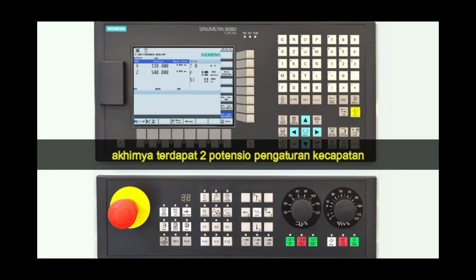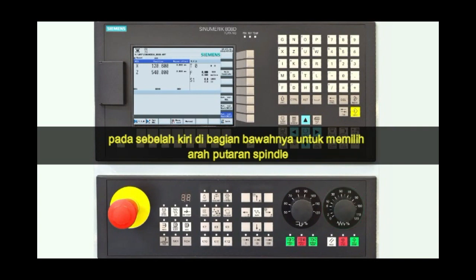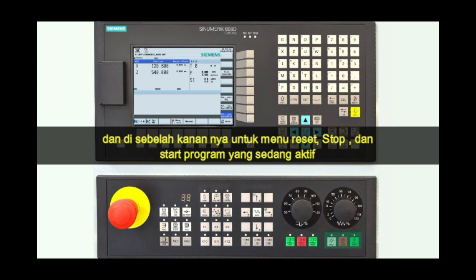Finally, there are 2 override rotary potentiometers. The first one is to influence the spindle speed and the second one is to influence the feed rate. The buttons below on the left side select the direction of the spindle rotation. On the right side you can reset, stop or start the active program.